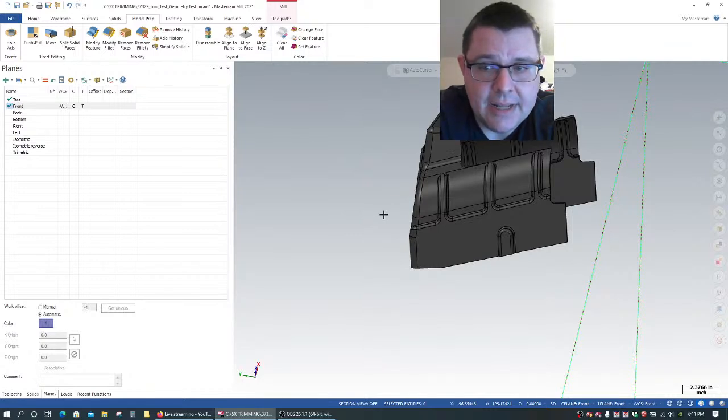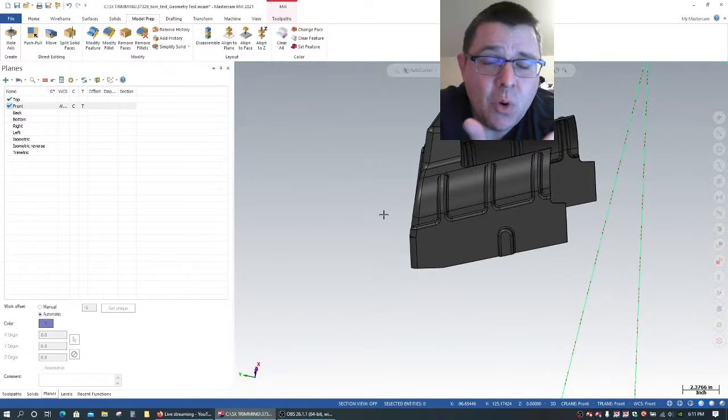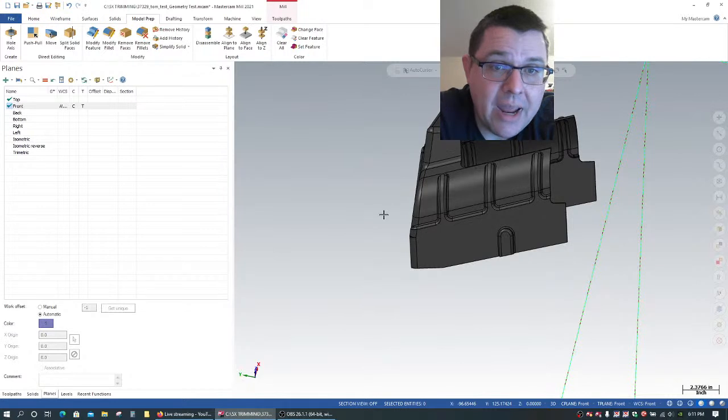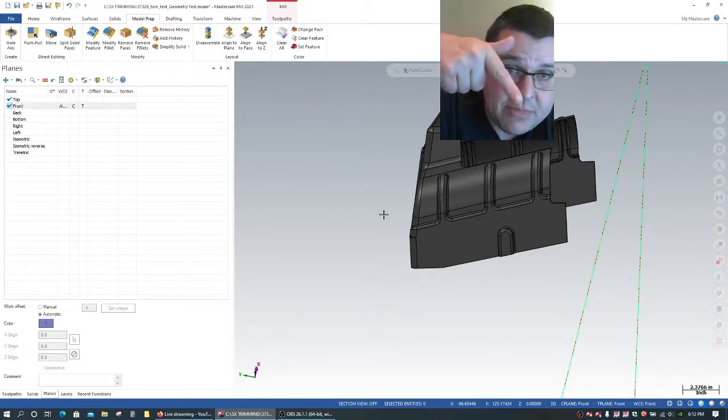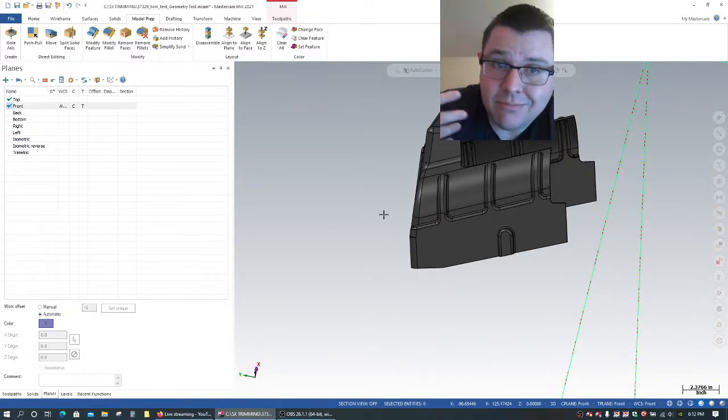And internally inside the post takes a look at how our plane is oriented in relationship to our WCS matrix. So there's a couple different matrices involved. We use vector and matrix math in the post to resolve the rotary angles and figure out if I'm tipping my head, in your case, or if I'm rotating my part on the table, in another case, right?